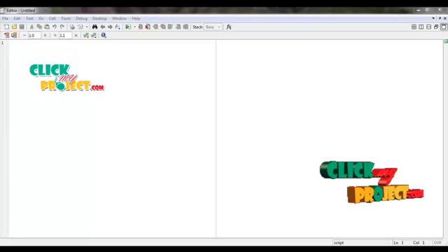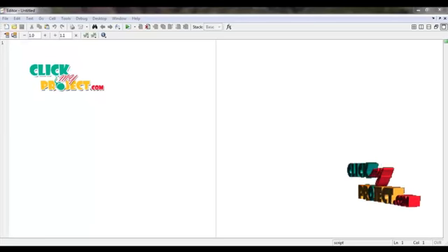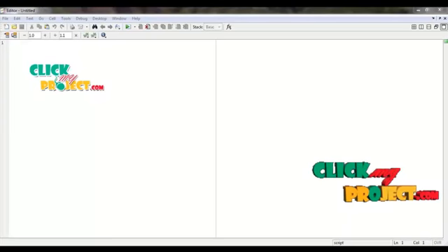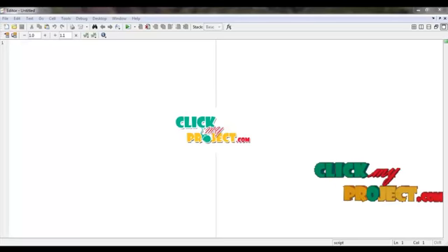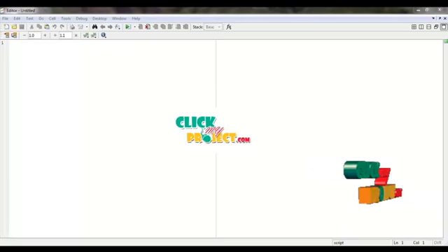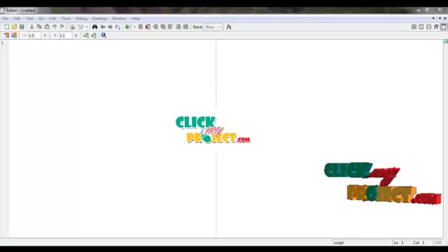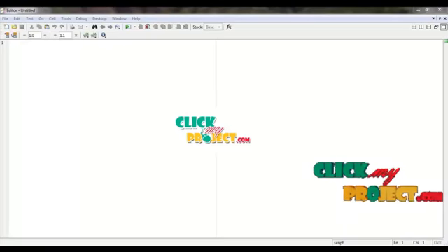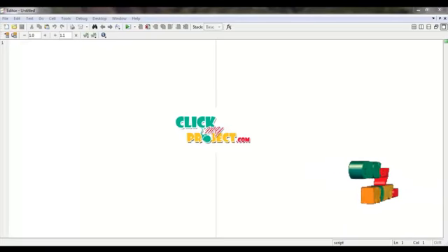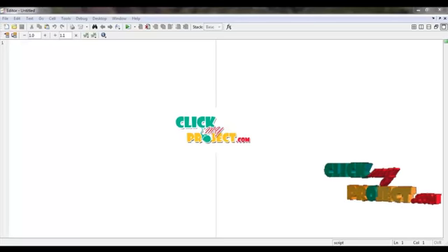The DC will go to the DC to AC inverter. The AC in that inverter will be controlled by using PWM. The PWM will be controlled by using the control signals. After the inverter, the 3-phase AC source will be connected to the measurement port. After the measurement port, it will go to the induction motor. Now we get the reference signal from the measurement port, which is used to calculate the voltage and current of the induction motor, and that will be connected to the DTC control scheme.